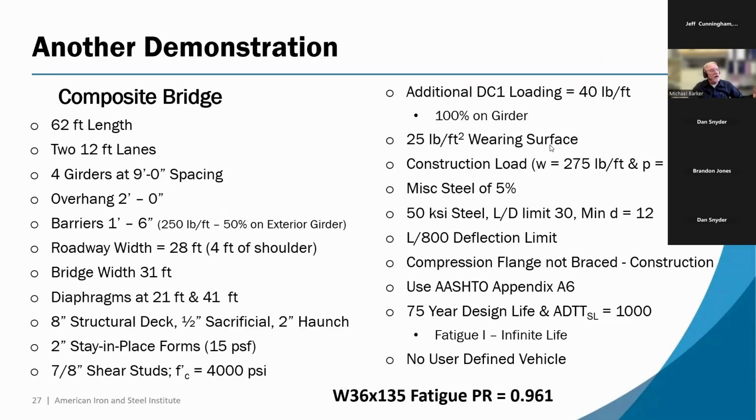The rest of it, yes, I'm going to put a little wearing surface, a future wearing surface. I'm going to consider that. But now I have that construction load up here where I'm kind of wiggling my cursor. And that causes torque on the outside, which puts lateral flange bending into my external girder top and bottom flanges. And there are requirements for that in AASHTO.